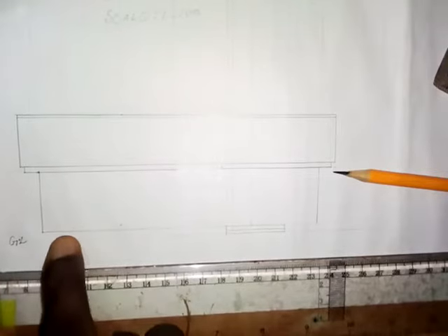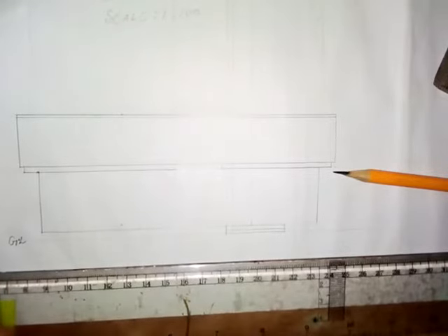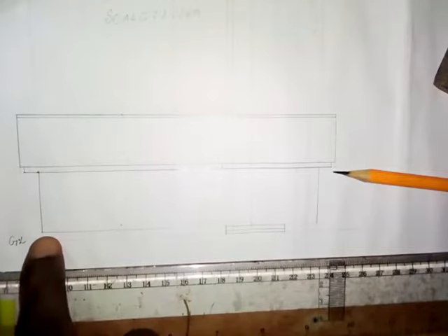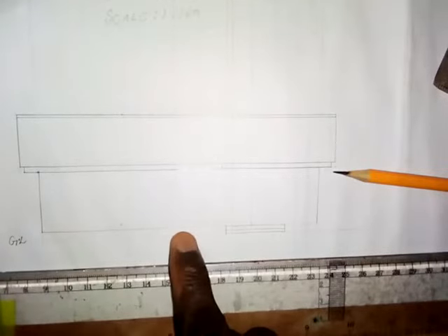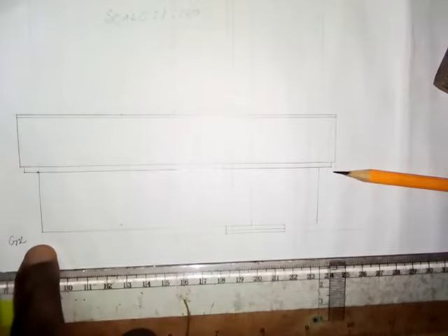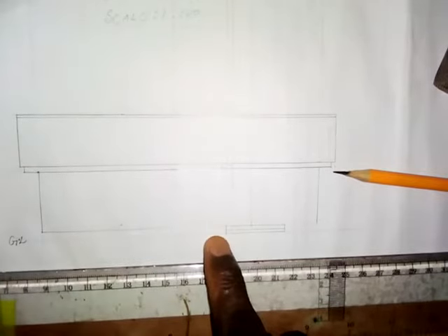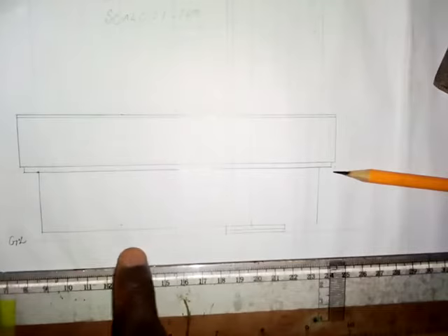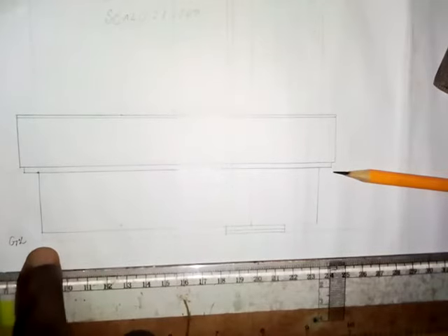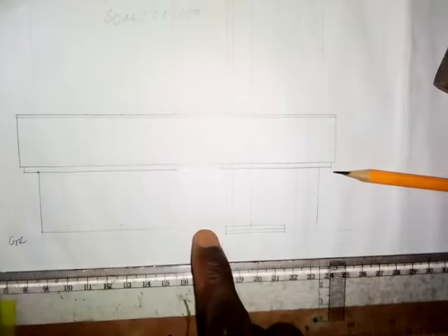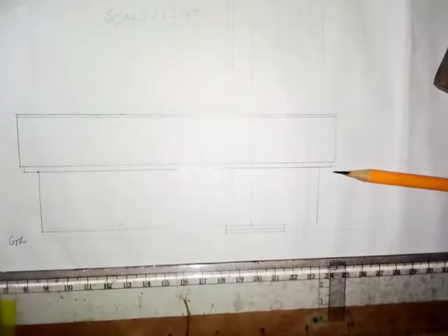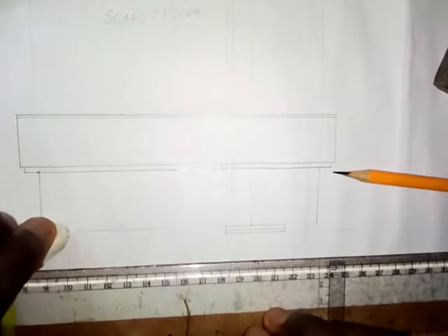This line that we have here, I need to clean it. This line is not supposed to be thickened, and this other line, I need to thicken it because this is the ground floor. Why is this line supposed to be a short dashes line? Because it will represent the finished floor in the building that we cannot see. We can't see the finished floor from the outside, so it will be hidden from us. So I'm going to make it a short dashes line.